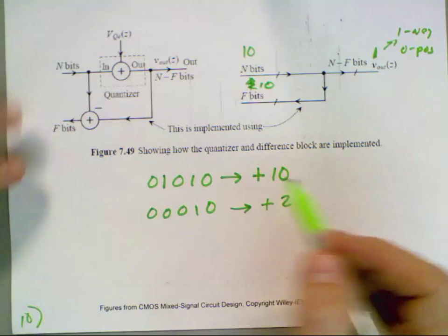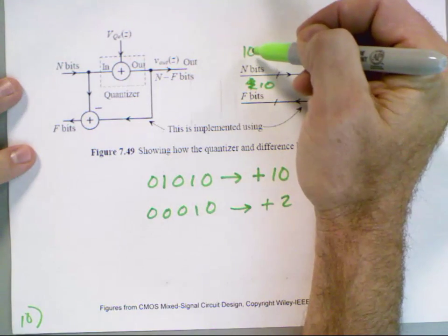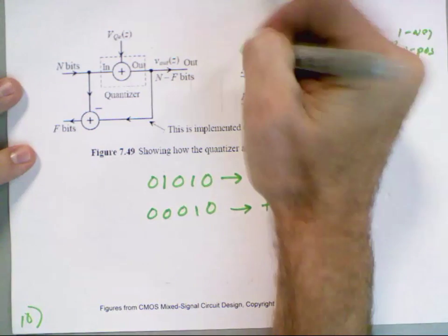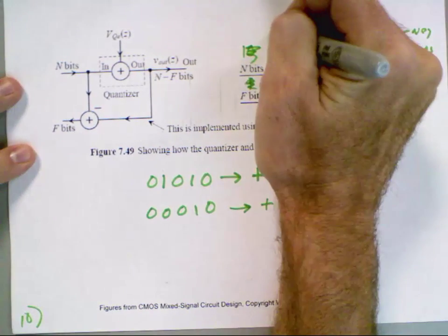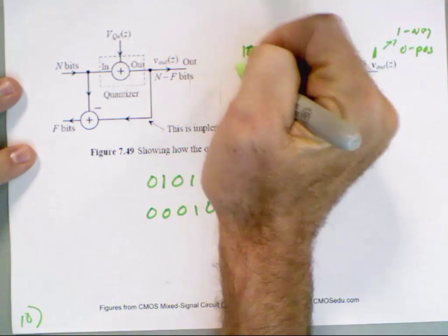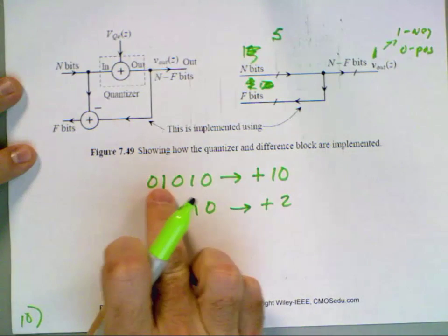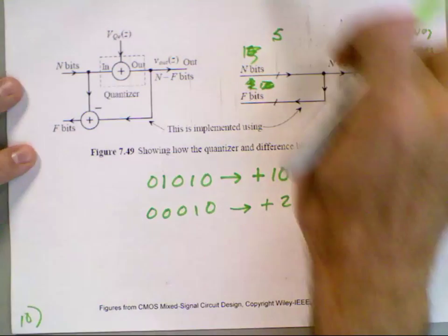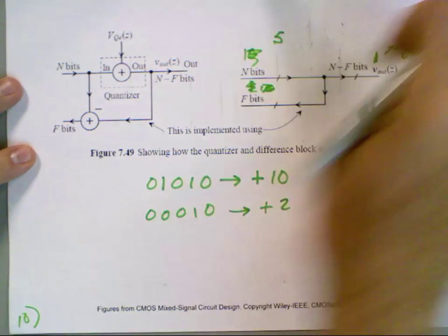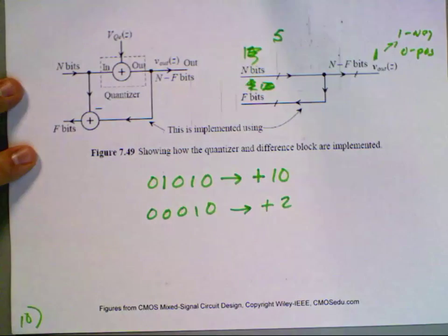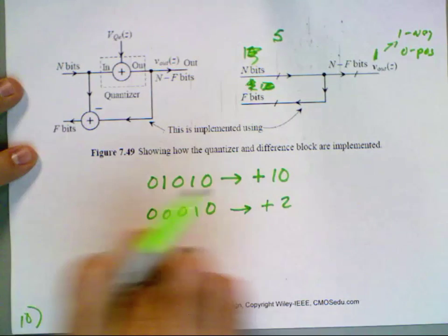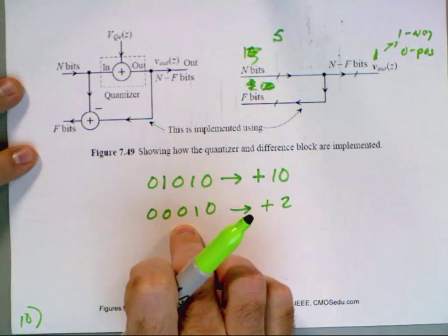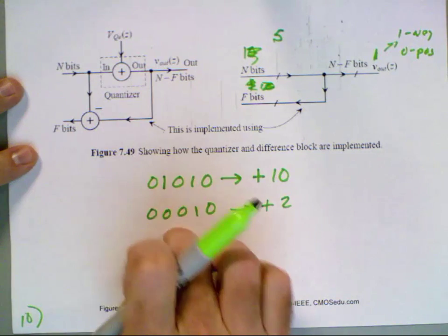No? So, okay, let's just use 5 bits instead, right? So I have coming in here this number, 0 1 0 1 0, okay? I strip off the MSB, which means I feed out a 1, and then I feed the output word back, and I subtract this from this. So I have to keep the word size the same.